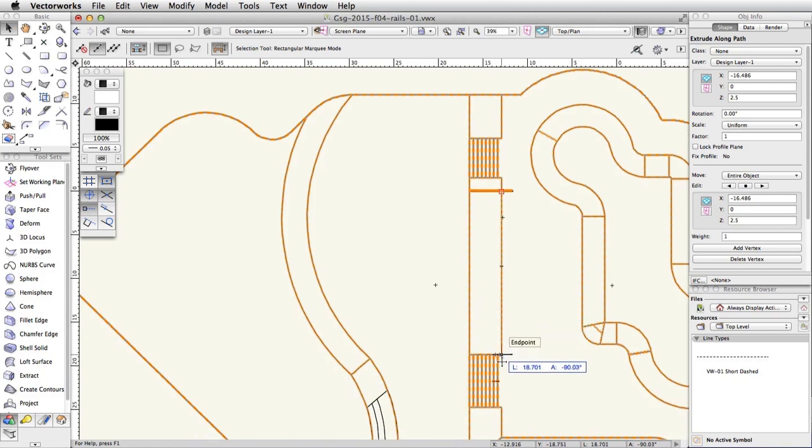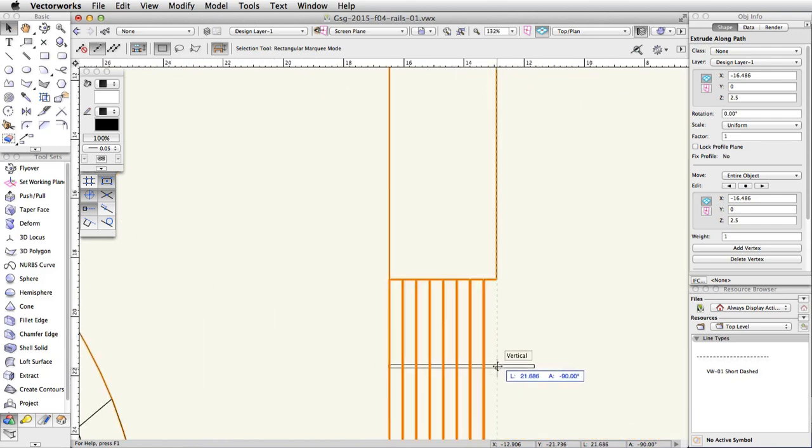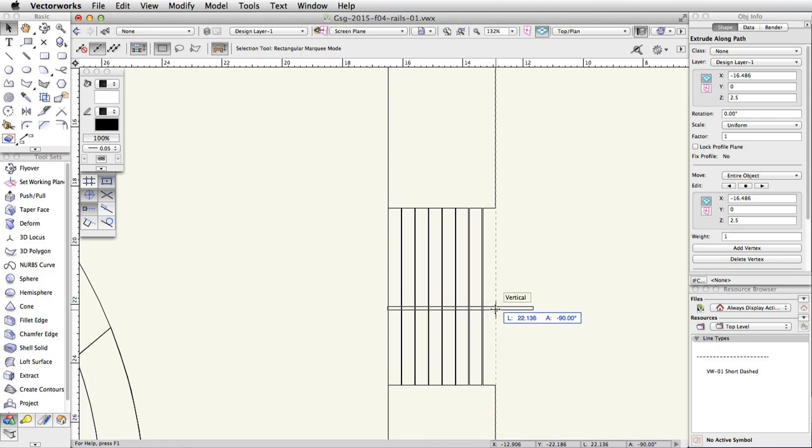As you move the rail down, you will see a dotted green extension line appear, and the vertical Smart Cursor cue will be visible. Use this line to maintain the x-coordinate of the rail. Move the cursor over the midpoint of the top step. After a few seconds, a red box will appear indicating that a smart point has been set. Move the cursor to the right along the horizontal dotted red extension line until you intersect the vertical dotted green extension line. When the Smart Cursor cue vertical/aligned V appears, release the mouse button to place the rail.